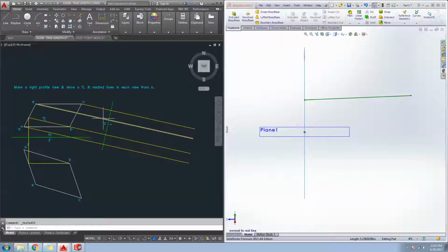Now, the next step is we're going to offset. We're going to go 2 views back, so this is the view we want. 1 view, 2 views, so this is the view we'll be measuring from. Offset, take the line A to here, here to here.